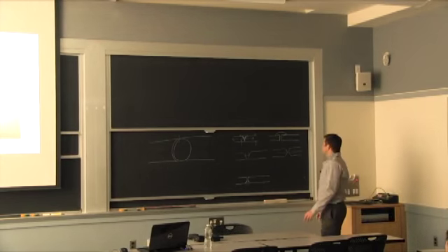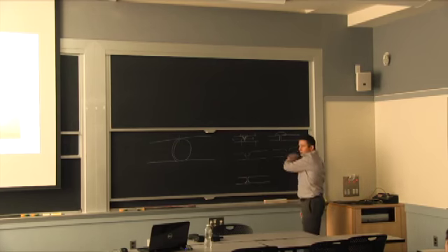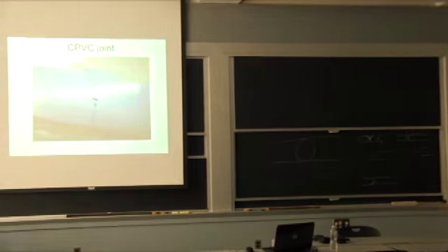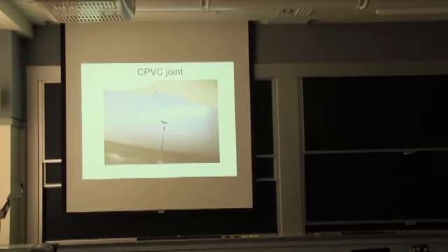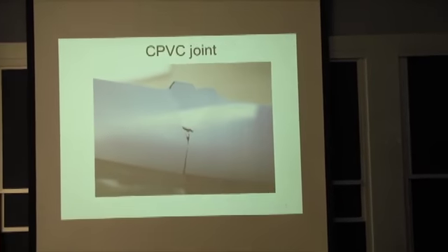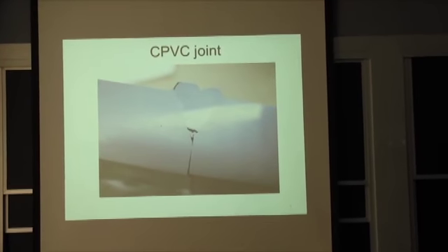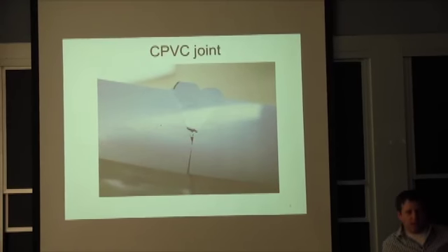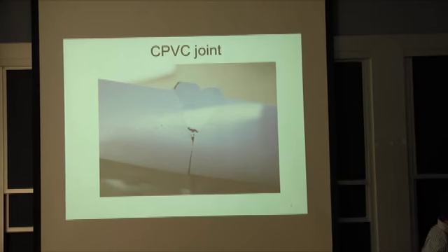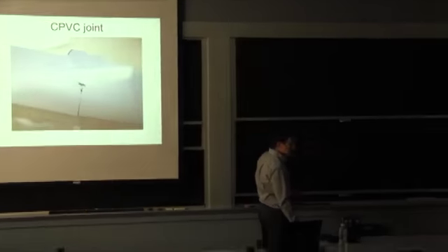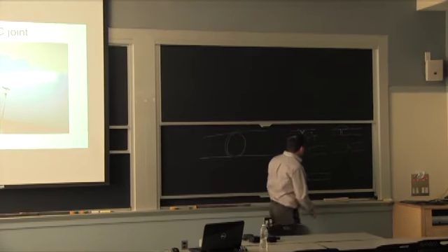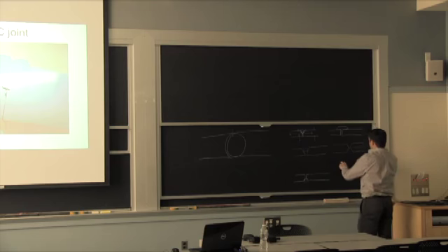So this is all essentially geometrical, what we've been talking about. But the point I was making in our last lecture about plastics is this is really melting the PVC in more or less ambient air. So they come with a heat gun and they provide heat. Say we're trying to do this weld right here. We're doing the root pass here.